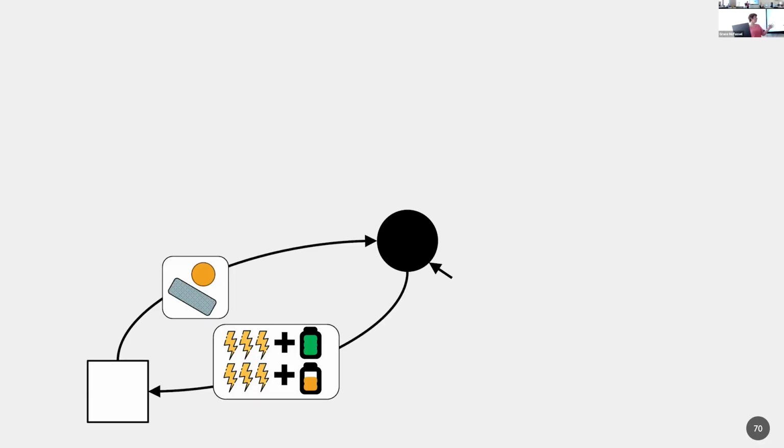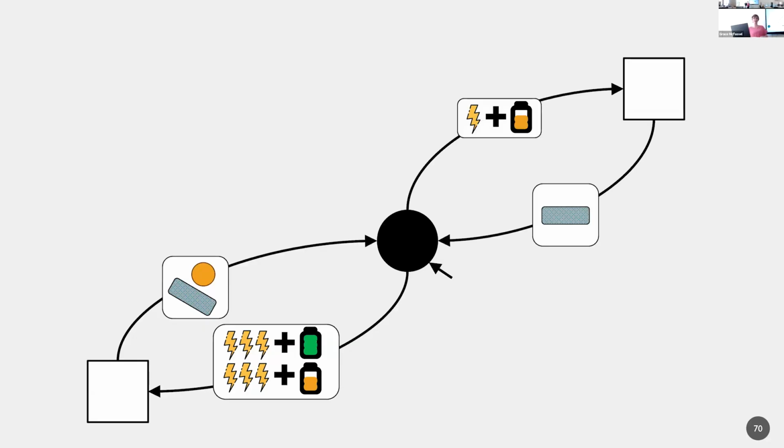To start, if power demands are really high on our robot, we might want to prioritize keeping our battery topped up so we can have this sun following behavior where we're constantly trying to maximize the input current that our robot receives. But if the battery is at a decent level and our power demands aren't too high, then it might not be worth it to do that. And we might just want to lay the solar panels flat and collect the sun from whatever angle it's at, and that's our lot.